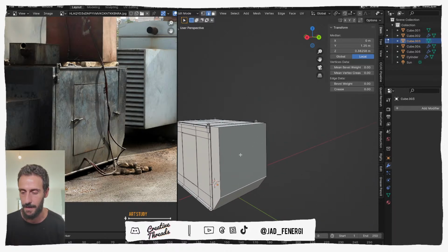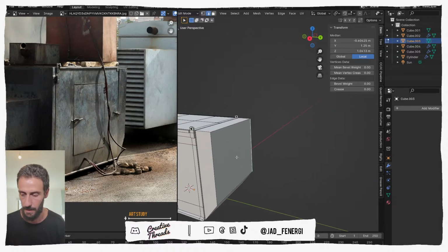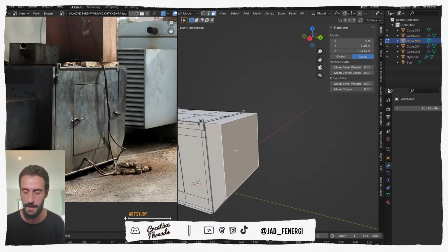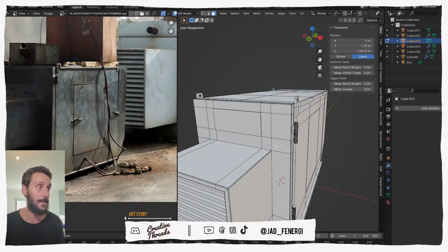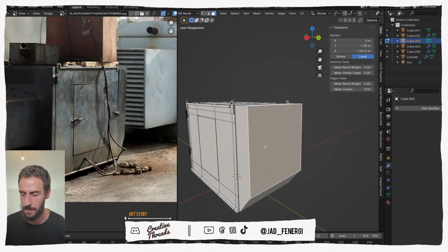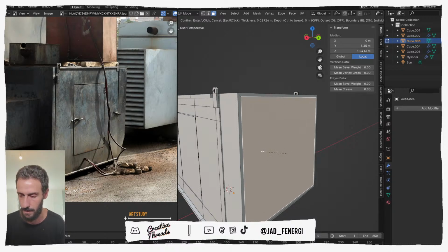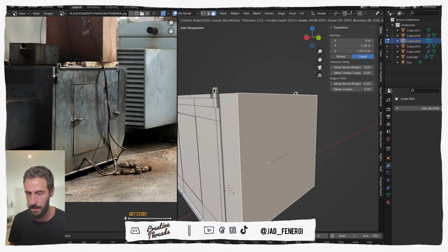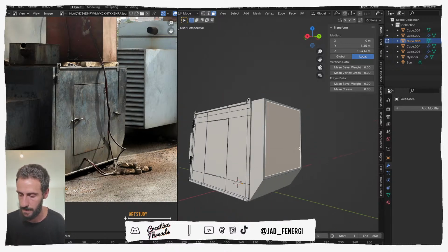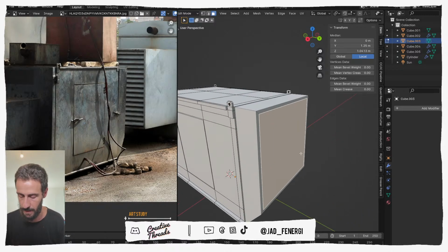And I think I've seen enough generators to assume that if we select this face by pressing 3 and we inset, I think this one has also fins, like the front ones. So this is for air circulation, because it gets so hot in these combustion engines. Now I think we can do something like 4 centimeters for this. My numlock is not on, so let's do inset 0.04 for 4 centimeters. Yep, I'm gonna E to extrude it inwards a bit.